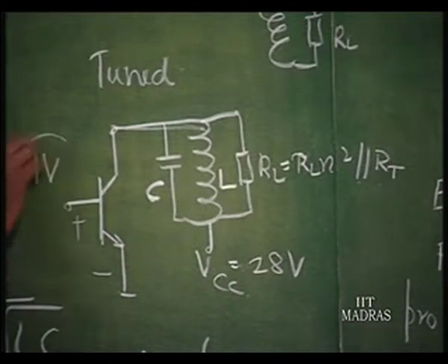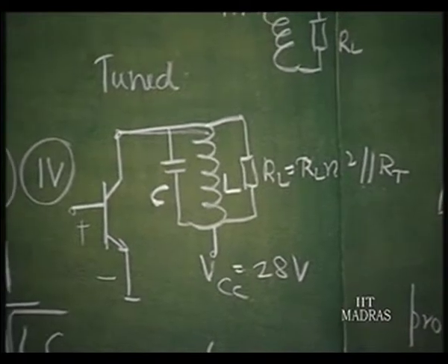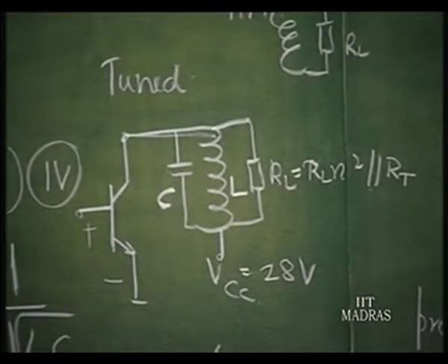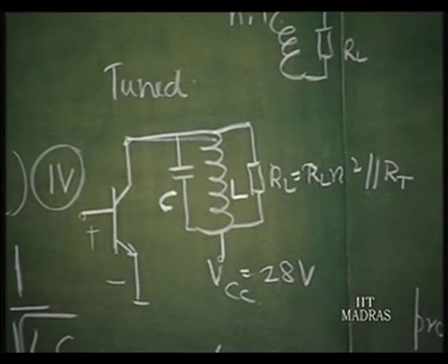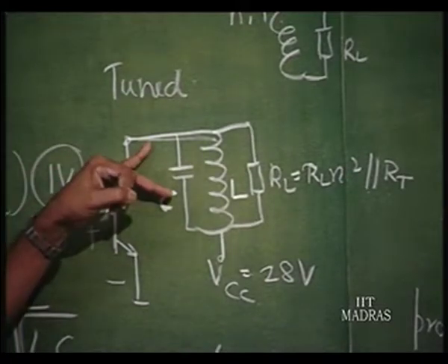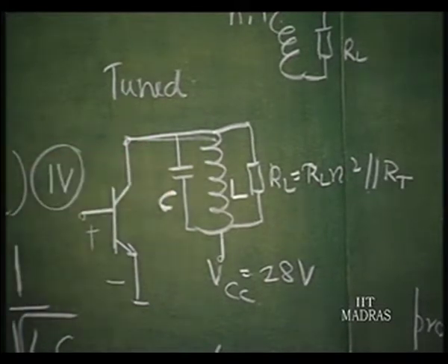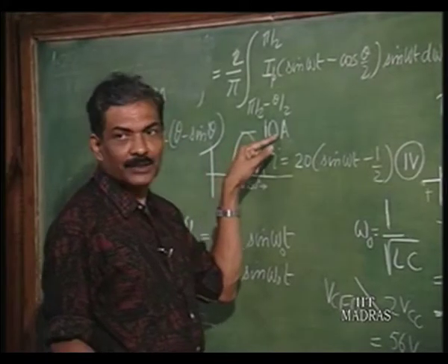So, you have to take this from the specification for the device. They will give the input characteristics, and from the operating current we know that the collector current has to go to a maximum of 10 amperes here.